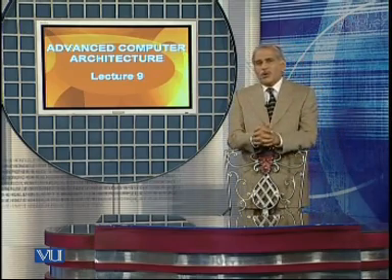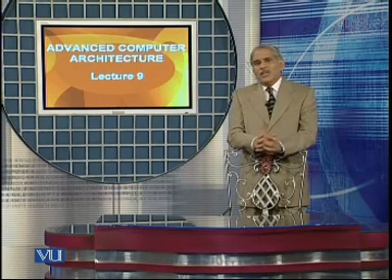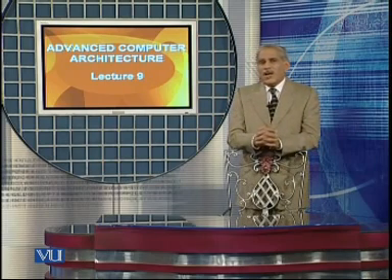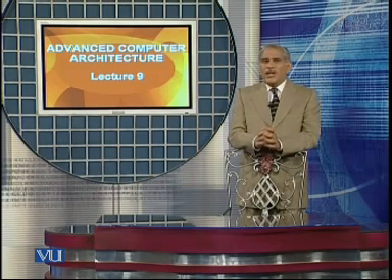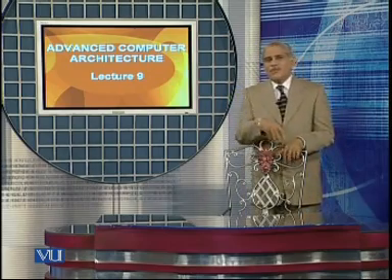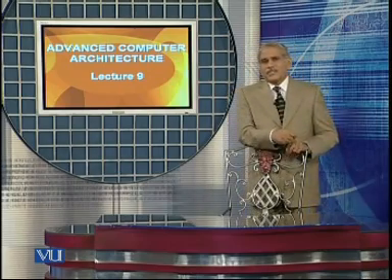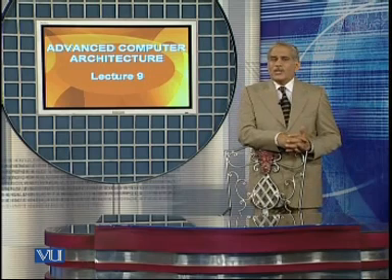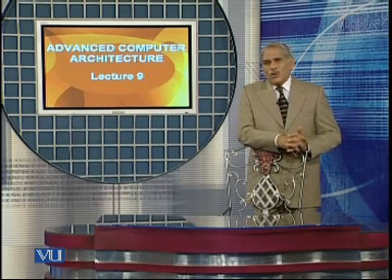If it is a load or store instruction, the execute is the address calculation, and the next step will be the memory read or memory write operation. Whereas if it is a register type instruction, the memory operation is skipped and the write back operation is performed.